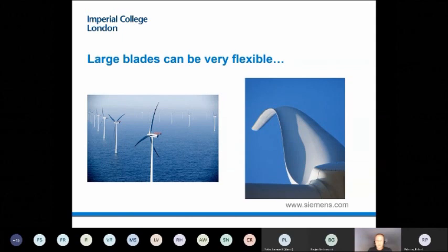One of them is you might look for stability. You might look for those to increase performance at very high winds. You let them deform in the right way. So what I will talk about at the end is called aeroelastic tailoring, when they deform such that actually you dump loading. Therefore, you can keep increasing velocity. So there are features that you can embed once you have the ability to actually design a system with flexibility. But the short answer is you rather wouldn't have it if you could avoid it.